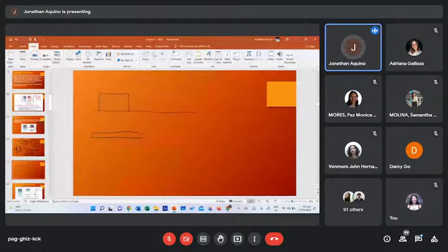So our centroid is 171.71 millimeters. Then the centroid of the transformed area is 425 minus x over 3, which is 367.76.